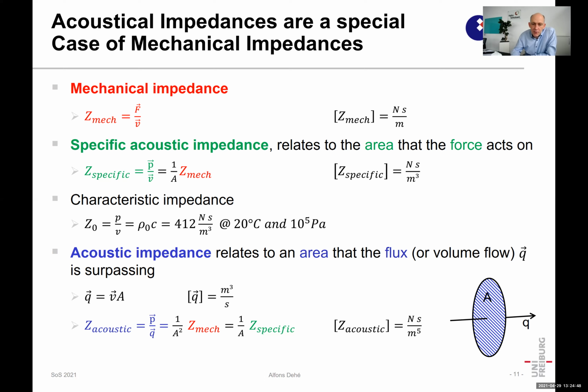So if you start doing modeling, also in the lumped element situation or with analytics, and you collect equations from literature, for example, say microphone, speaker, whatsoever you want to design, and then you are looking for a specific calculation, be very careful, because very often specific and acoustic impedances are mixed in there, and if you do not calculate your dimensions, you can be quite wrong, because it's always area or dimension squared, which is then wrong, and you get messy situations in your early calculations.